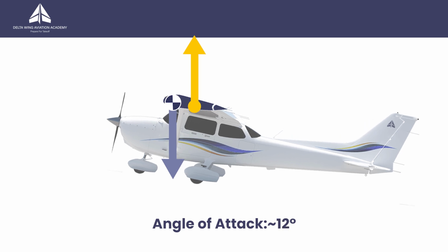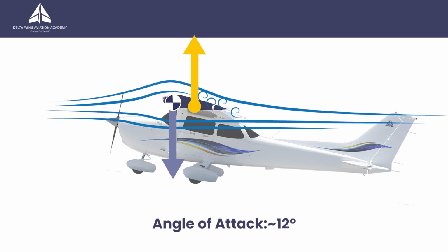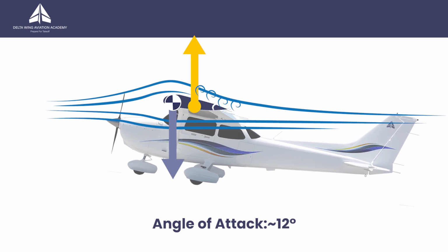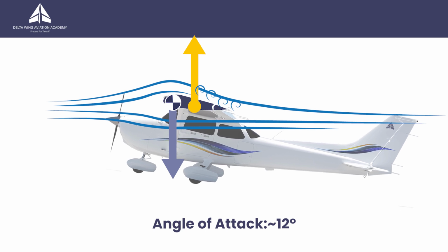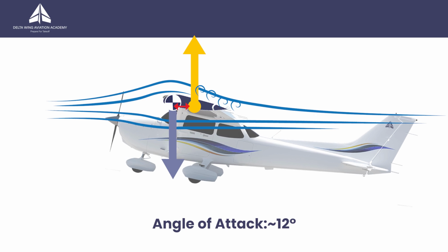Further increasing the angle of attack causes the top airflow to become more turbulent at the trailing edge and start to separate away from the wings. Most of the lift is now generated near the leading edge of the wings. Thus, the lift vector moves further forward, closer to the weight vector. Consequently, the aeroplane becomes less stable since the moment between lift and weight reduces.